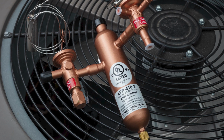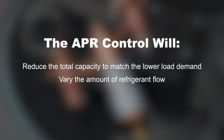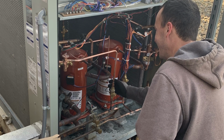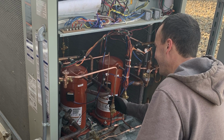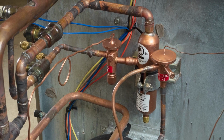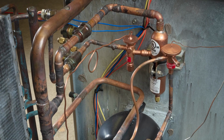Here's how the APR control can help. The APR control will reduce the total capacity of the DX air conditioner to match the lower load demand in the space. The APR varies the amount of refrigerant flow to the rest of the circuit when needed, resulting in reduced capacity at the evaporator coil to avoid overcooling. Varying the flow of refrigerant will result in extending the runtime of the compressor while also keeping the evaporator coil face active and below the dew point of the entering air, allowing the unit to stay in dehumidification mode by preventing the thermostat from satisfying too quickly.